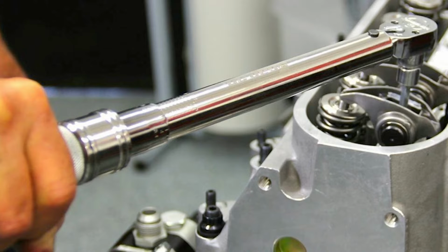Torque wrenches are used for this purpose. The torque required to attain a specified tension in a bolt of a given size and grade is determined by tightening this bolt in a tension indicating device. This calibration must be done daily during construction for bolts of each size and grade.